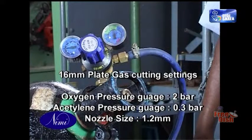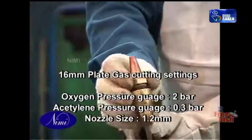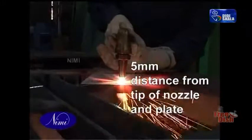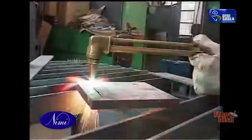As the plate thickness is 16 mm, set the oxygen pressure to 2 bar and the acetylene pressure to 0.3 bar. Mount the nozzle on the blowtorch. Follow all the procedures you have learnt in earlier exercises while cutting.